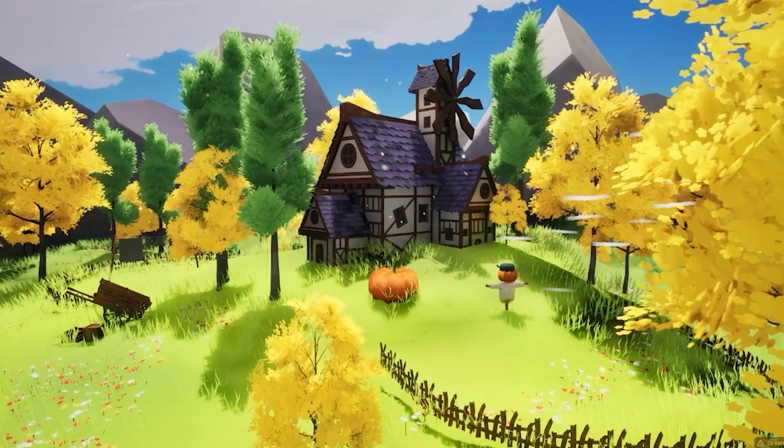The dots which you see are cubes, which were now on the land but didn't feel natural at all for the grass to be implemented. To fix this, I changed the point extents of the surface sampler, which minimizes the squares to be more editable for the next nodes. From here, I'm able to add a spatial noise node to replicate density for my grass, since grass in nature can vary from light patches to very full ones. The black squares showcase how dense the grass will be for our final product.